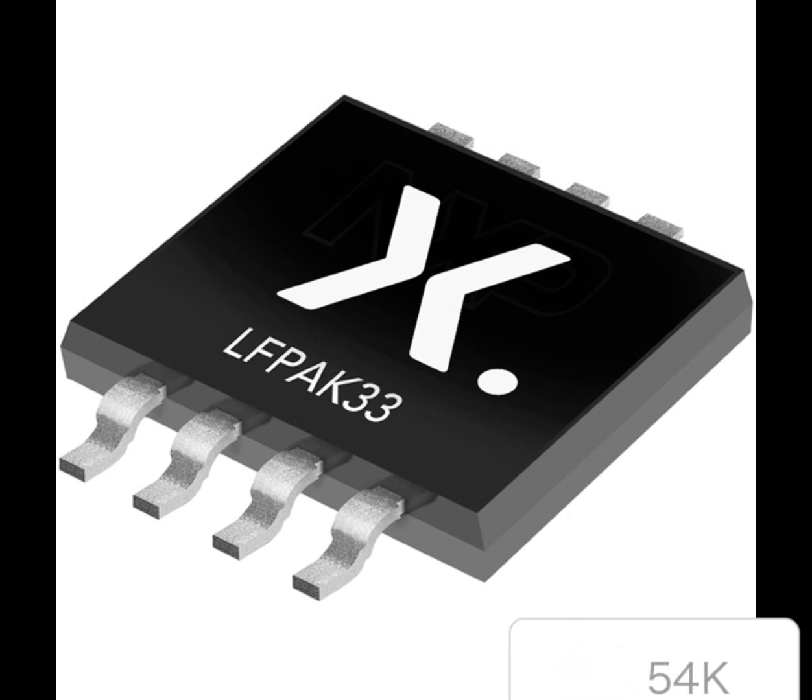However, creating industry-compatible doping methods and controlling the polarity of these devices is a complex challenge. These top-gate complementary carbon nanotube MOSFETs have been developed using localized, conformal, solid-state extension doping to determine the device polarity and ensure balanced performance. In these transistors, the channel remains undoped.